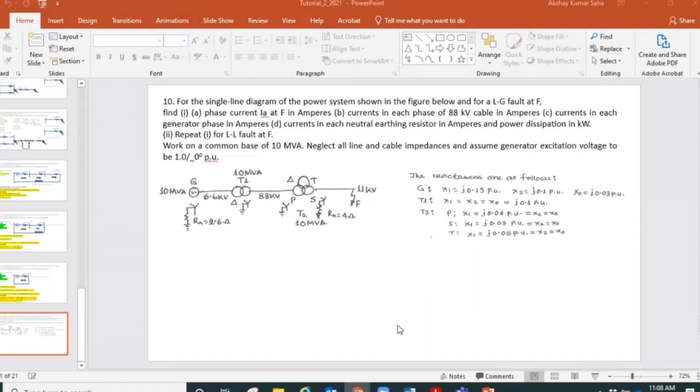First harmonic, second harmonic, so 100 Hz. Third harmonic, multiplied by 3, you get 150 Hz. Multiplied by 4, you get 200 Hz, and so on. So we see 100 Hz, 150, 200, 250, 300, and so on. All these are harmonics now. Fundamental and then harmonics.